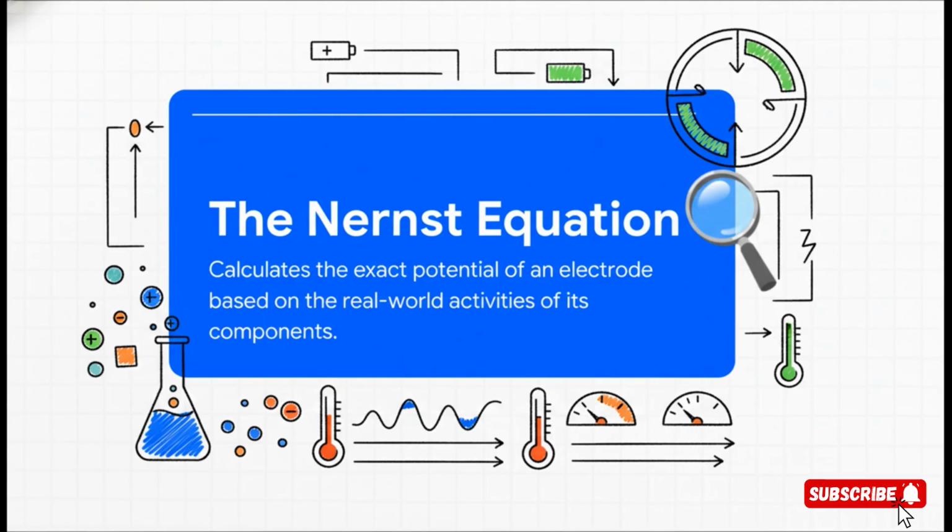Okay, so those galvanic series tables are awesome for a specific environment, like seawater. But what if your pipeline is buried in soil that has a totally different ion concentration? Or what if it's operating at a higher temperature? We need a way to adjust those standard lab values for real-world conditions. And that is the power of the Nernst equation. It's the formula that lets us fine-tune our theoretical predictions for the messy, complicated reality we find out in the field.